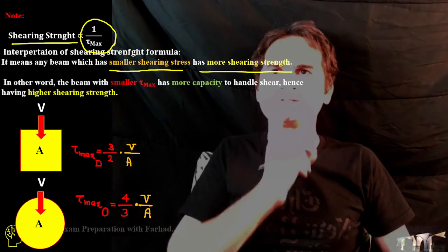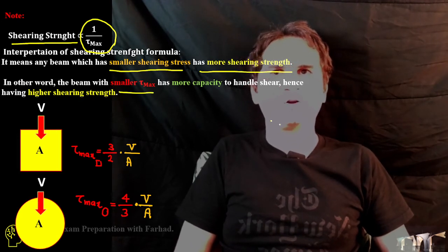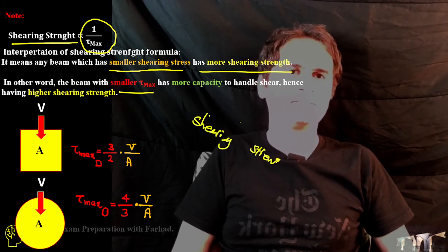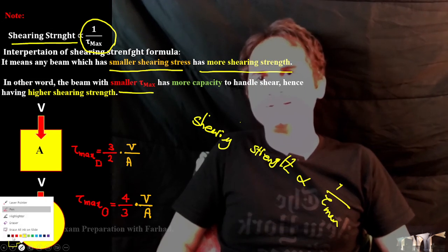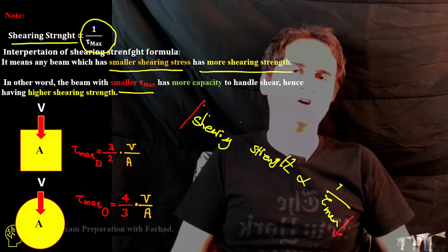In other words, shearing strength has a relation with 1 over tau maximum. It simply says any beam which has lower tau maximum has higher shearing strength.